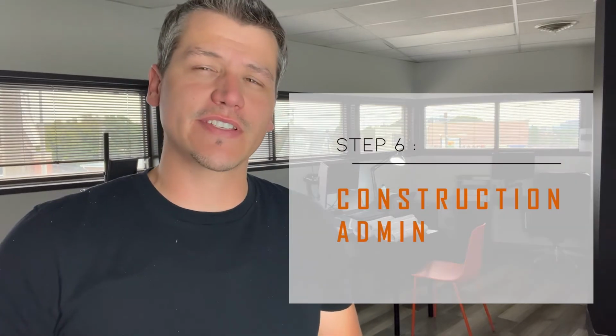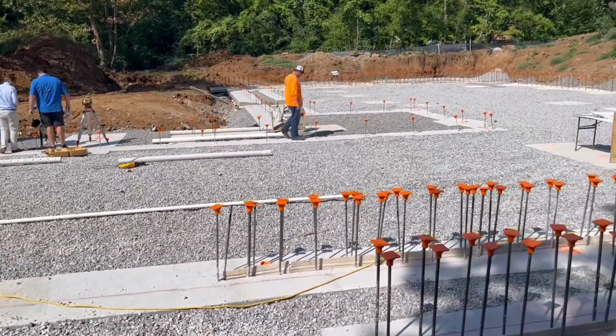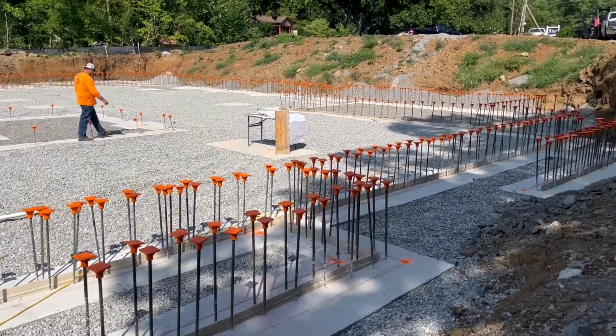apples to apples comparison. Construction administration is the final step for the design process, and it's not to be confused with construction management. Architects are not typically involved in the management of bringing methods and materials to the site. Important distinction there is that during construction administration, the design team is going out to the site and making observations and seeing how the constructed product compares to the design intent. Any variations found during the construction process by the designers that differ from the design intent, what's on the construction documents and the specifications, are simply reported to the owner as a variant.